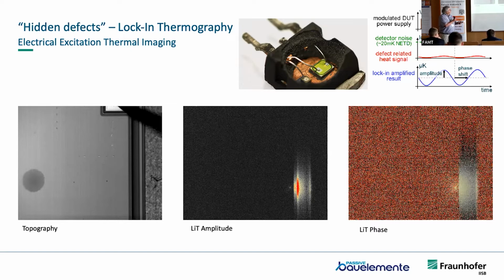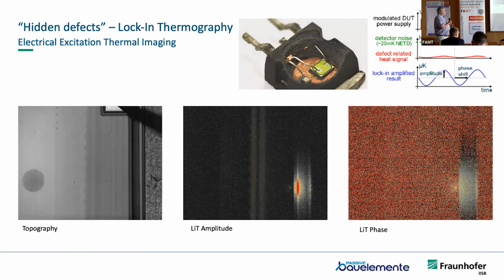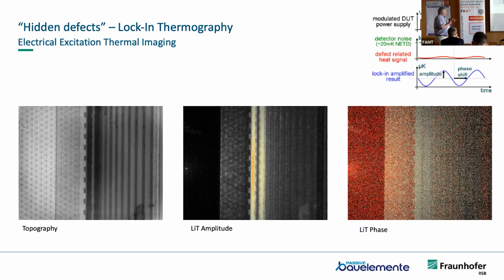The funny thing is, in principle, you can look through polymers, really inside. You don't need to have a flat surface. It's a very useful method for our type of products to analyze, just by the heat-induced rise of temperature, where a potential defect could be. And here are other examples.